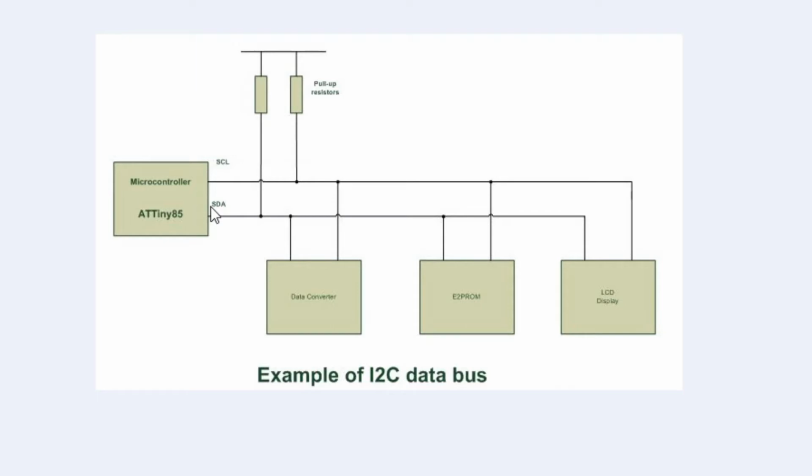The logic part of it wants to pull it down. It will activate the FET transistor, and that will provide the shorting path to pull the line low. When you want it to go high, the slave or the master releases the FET or the transistor by turning it off, and these resistors will then pull the bus high. The lower the capacitance on the bus, the higher the value you can have. It's just you need to pull that high enough in the required time.